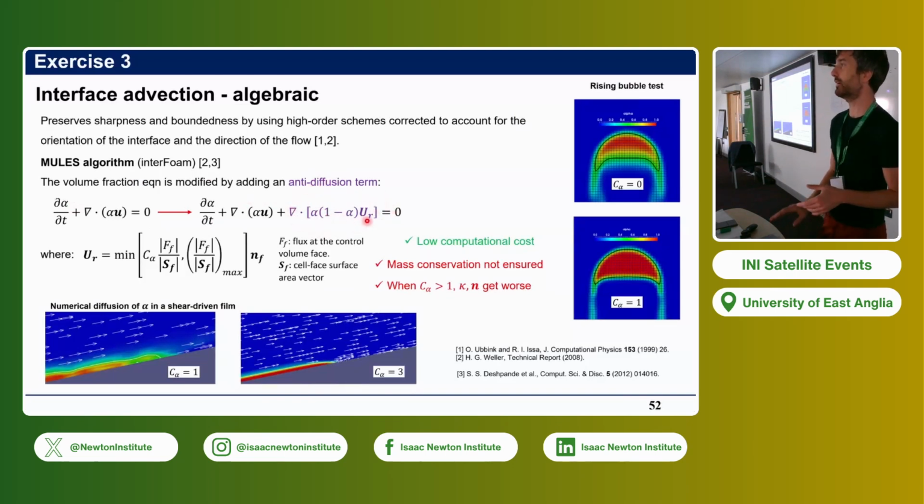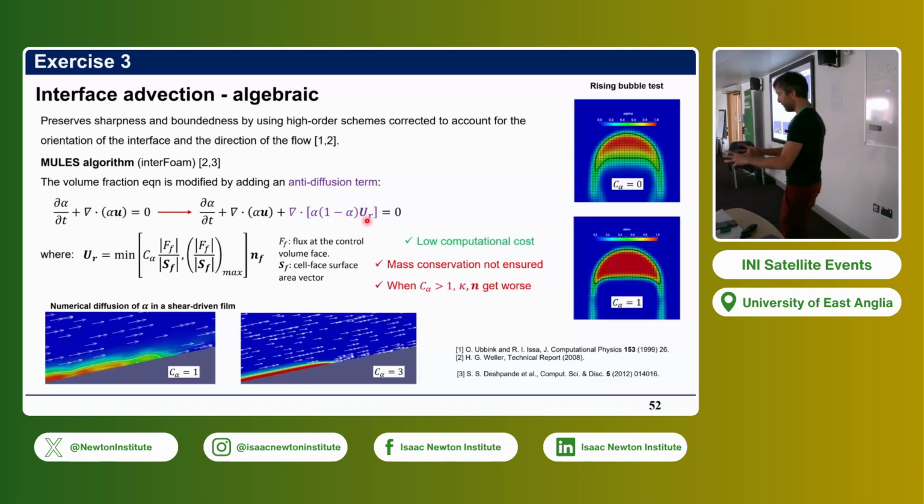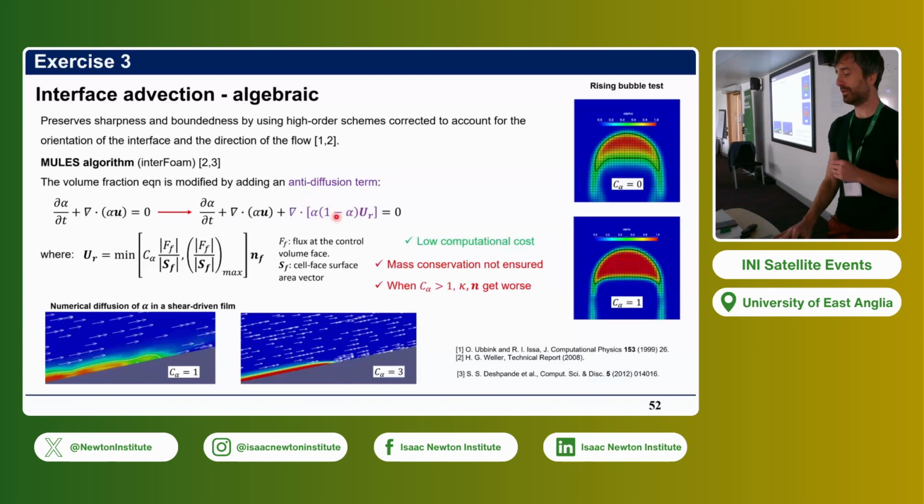This anti-diffusion term, you can imagine as making a tiny mountain of sand at the beach. The sand will fall off, and with your hands you keep bringing the sand back to the mountain so that it stays at the same altitude. So in a very descriptive way, this anti-diffusion term imposes a flux inward to the cell to counteract the spreading of alpha.